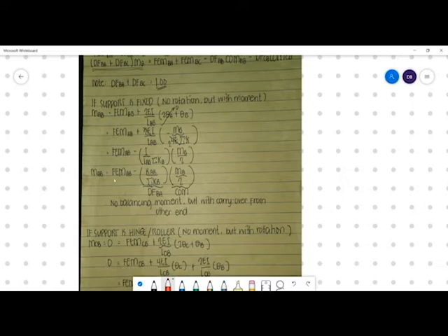So, inassume muna natin na they are restrained, and then wala tayong theta. Walang rotation, ibig sabihin, hanggang sa dulo, we didn't allow any rotation. So, therefore, there is no means of balancing the moment. Hindi natin binalance yung moment sa AB, kasi walang rotation na magaganap hanggang sa dulo. Pero at the same time, from support at B, meron tayong carry over na tinatawag. So with no balancing moment but with carry over from the other end.